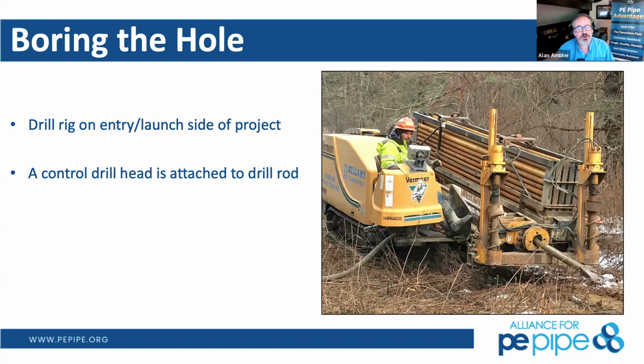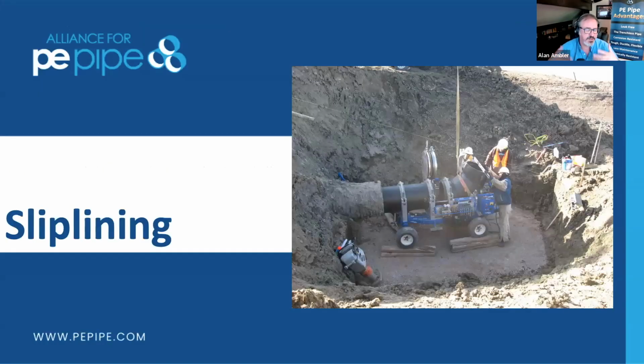The internal part of that hole, of course, is pressurized with drill mud, typically a bentonite with some additives and other things that keep that borehole open and also carry the cuttings that the reamer creates when removing soil or other material we're cutting through, and it circulates that back to the opening of the HDD hole for us.